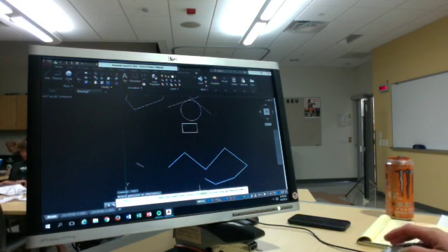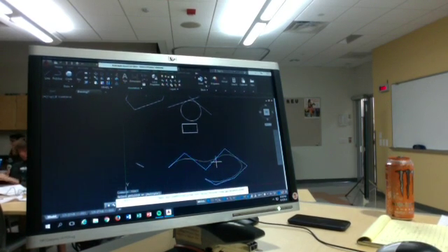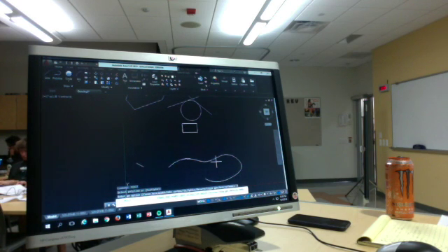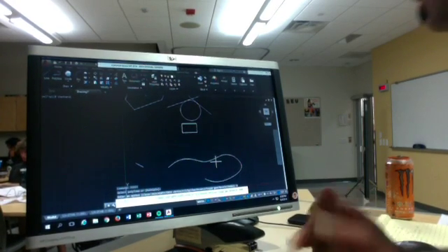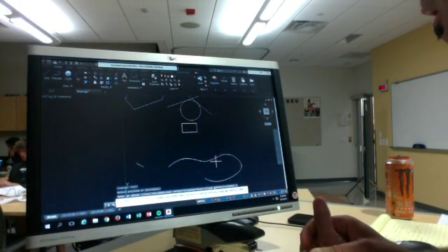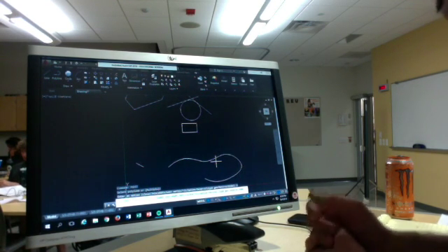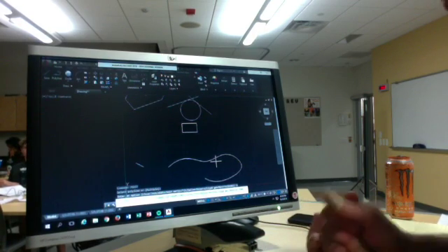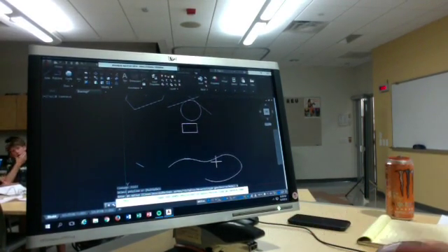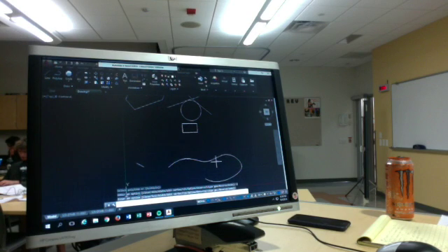So the spline here, you type in S. Oh, now it's a spline. There you go. So it really is that simple to edit a polyline, because sometimes you want to draw a polyline using points just to make sure that it's hitting the right points, and then change it into a spline in order to give it the right contour of the part that you're working on. One important thing, now that you've done that, you have to hit enter, or else it'll exit out of the command and not change it to a spline.